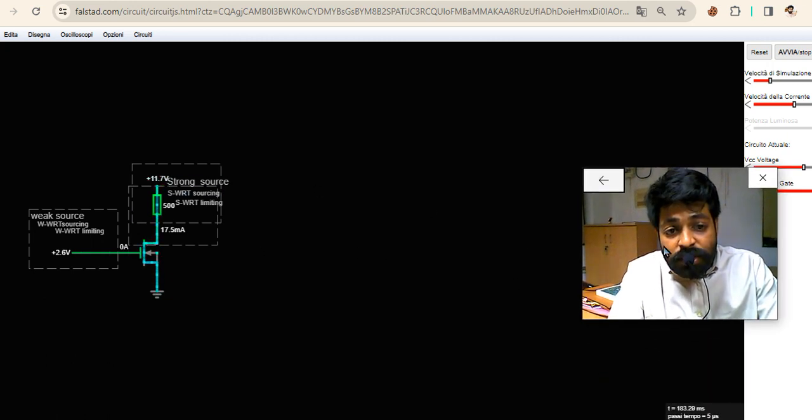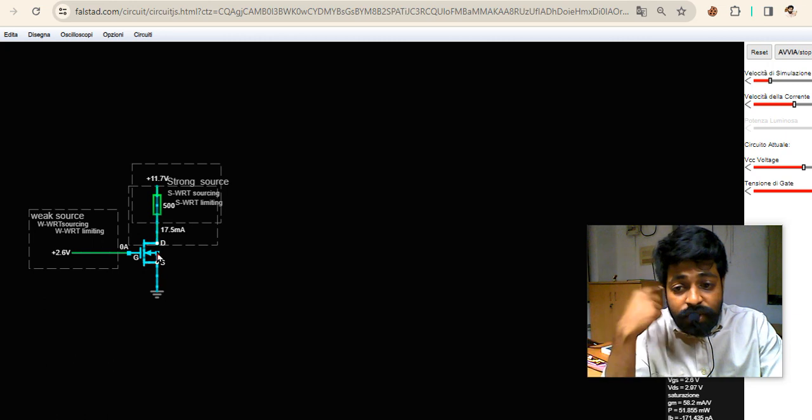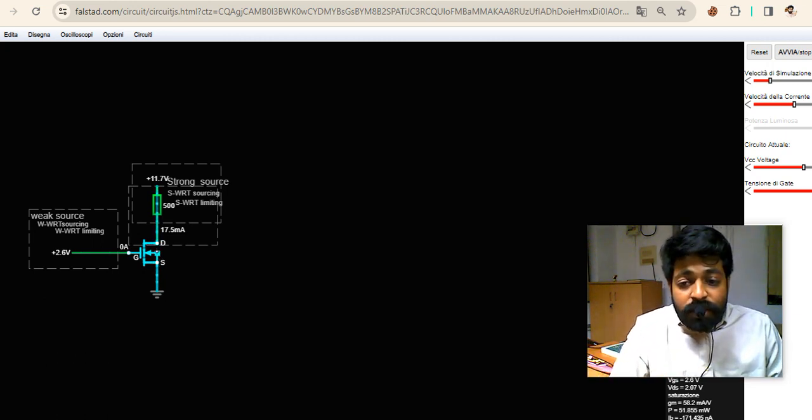So whatever changes you try to make, 11.7, now it is not changing. Even though we are changing the VCC, the current over here has not changed, because the current is controlled by this fellow. So the transistor has its control over here when sufficient supply is given. So now I can give the conclusion whether the transistor will do the control operation or not.